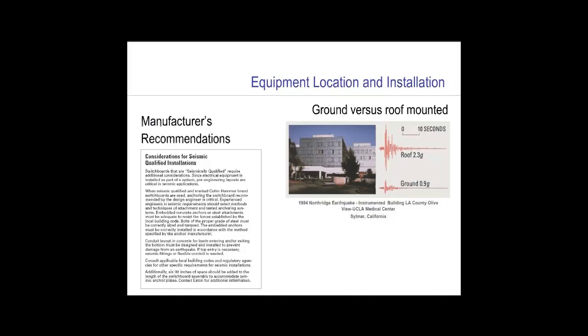The next topic we need to now consider and appreciate is this. The seismic qualified certificate is only as good as the installation employed at the project site. One must remember that equipment must be installed per the manufacturer's recommendations as found in the installation manual provided with the equipment. This requirement is also found in the 2008 NEC and CEC at 110.3(B) and 110.13(A). It is up to the AHJ, whether the electrical or structural principal, to verify that these installation guidelines have been followed.